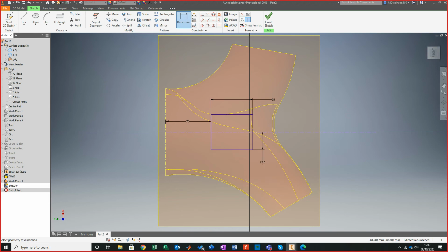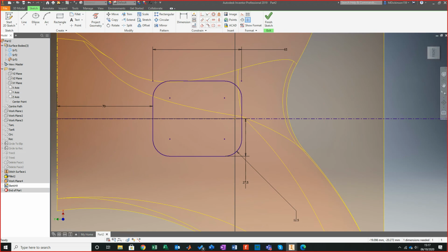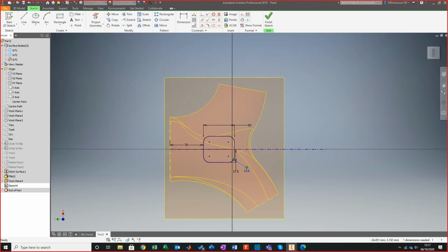And then the easiest solution with this now is just simply add a fillet. Fillet the whole edges, and these fillets are 12.5. So I go that edge, that edge, press Control, and that edge, and that edge, and that edge. Okay. So a way to speed that up, if you press Control, select the edge, it will apply it, you can just click as you're going around.